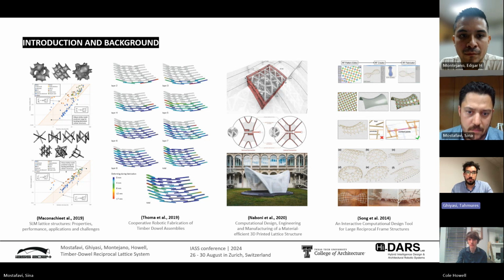Another important contribution comes from the research on the computational design, engineering, and manufacturing of a material-efficient 3D printed lattice structure. This work underscores the importance of computational tools in optimizing both design and material use in lattice structures. And finally, the development of an interactive computational design tool for large reciprocal frame structures allows designers to explore and optimize complex structural forms, driving innovation in architectural design.